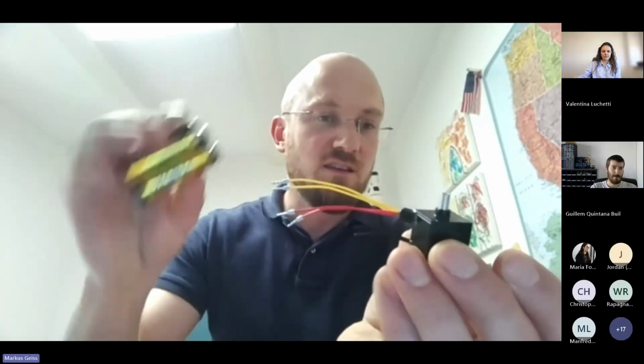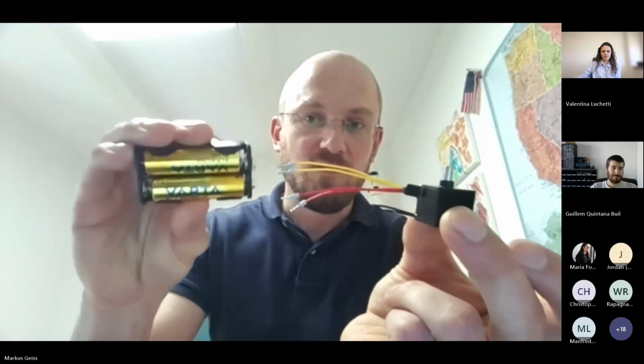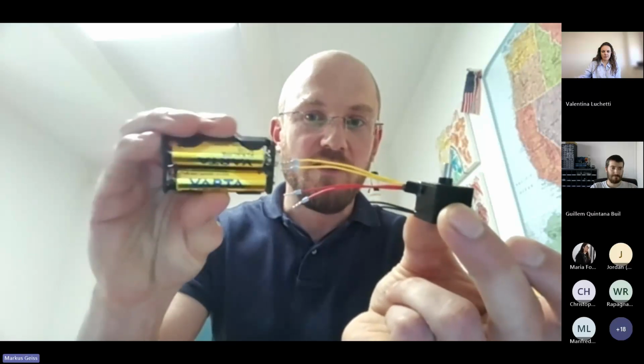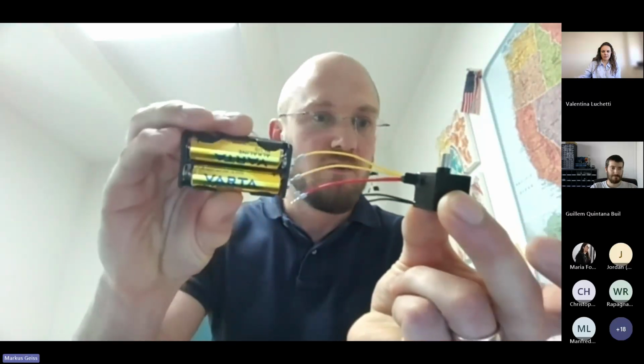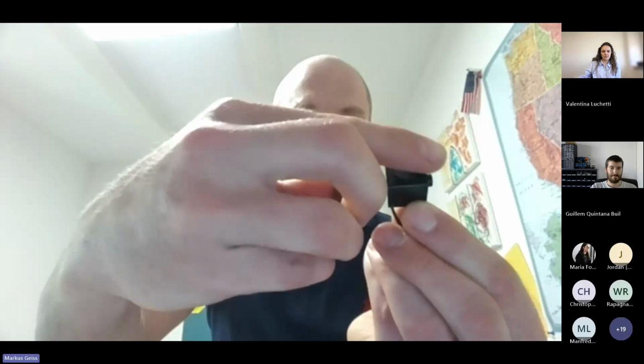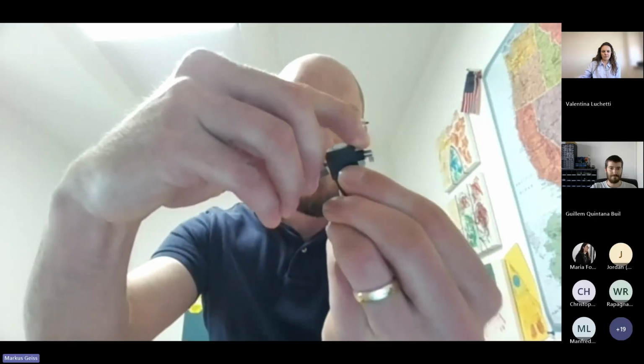And to show you how easy it is, all you need is some sort of a power supply. I just use my AAs to hook that up with one of the lines, and there it releases. After you've done your trigger, obviously you want to do tons and tons of testing. So a quick and easy and cheap reset is crucial. So what we supply you with is the tool you need, a mechanical reset tool. All you do is push that in through the back, and there you go. You're back in flight configuration, just like that.